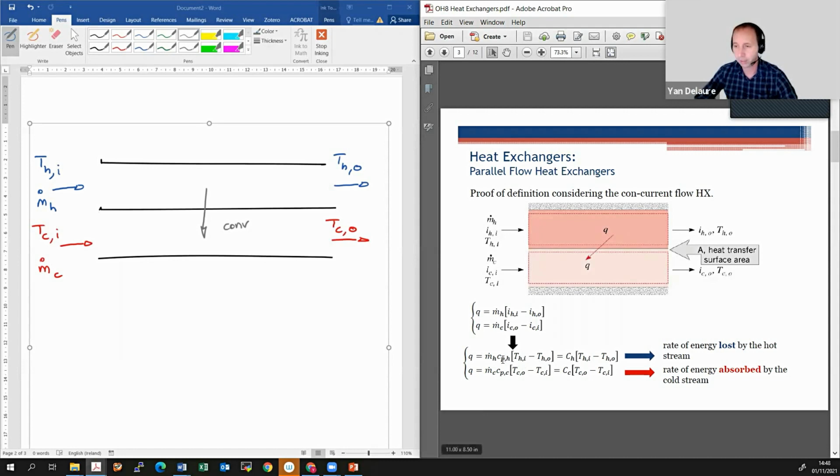So if you take Cp times temperature difference, it's the same as the difference in specific enthalpy for that incompressible fluid. It's a lot easier to think in terms of the temperature than the enthalpy. So that is why we're working with these equations here. What you need is a measure of the heat capacity. And then if you're thinking in practical sense, you need a measure of the temperature, and that's achieved by putting temperature sensors. That's fairly easily available technology. So no challenge here.